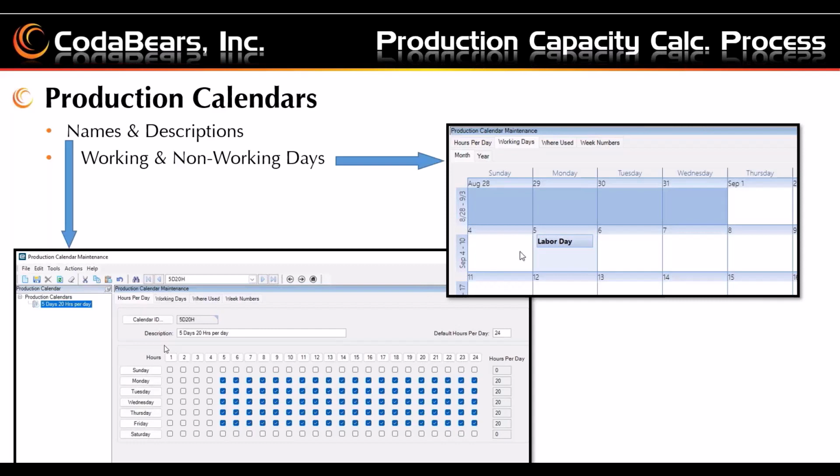One drawback with having multiple calendars is you have to maintain these calendars moving forward. Just because you put the holidays on the main calendar doesn't mean it's going to copy to all the child calendars that are out there. You need to maintain each of these. I believe somebody in the community had written a DMT and a BAQ that exported the calendars, allowed them to edit it in Excel, and then import them back into the calendars. Don't quote me, but I'm pretty sure that was posted on the Epicor users help.